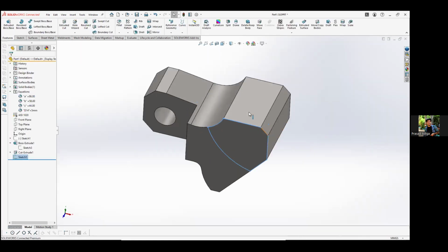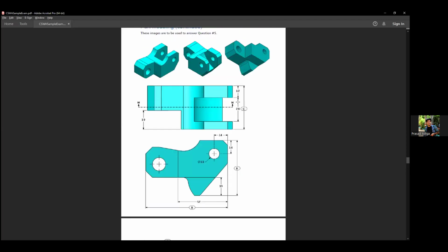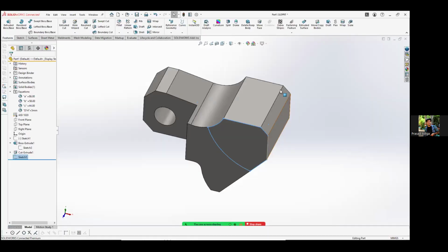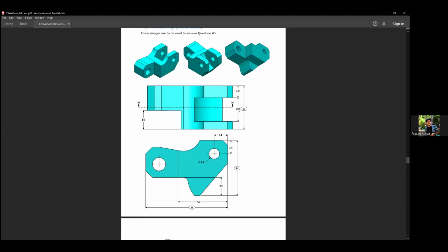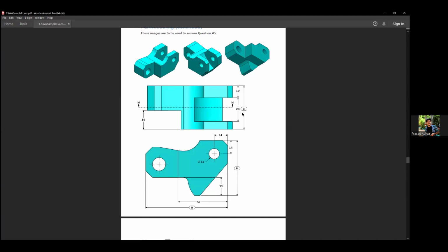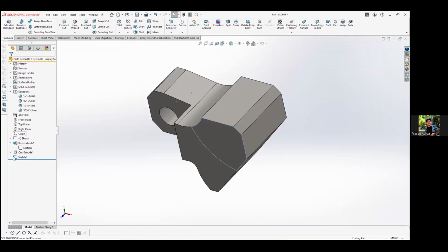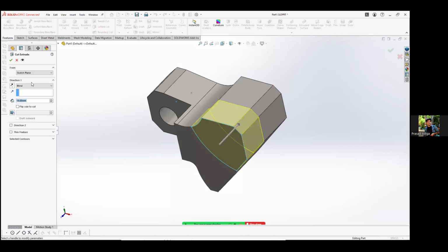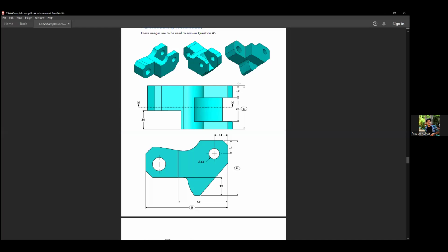Yeah, as you can see here, they have given 12 mm offset from the other side and 24 mm of cut, but they have not given this side. So as we know, C is nothing but 44. So this remaining section will be 44 minus 24 minus 12. Now what we'll do is we'll just go to select the sketch, cut. Now when I select cut from sketch plane, it just directly cuts. I don't want that to happen. We need an offset of C minus 24 minus 12.